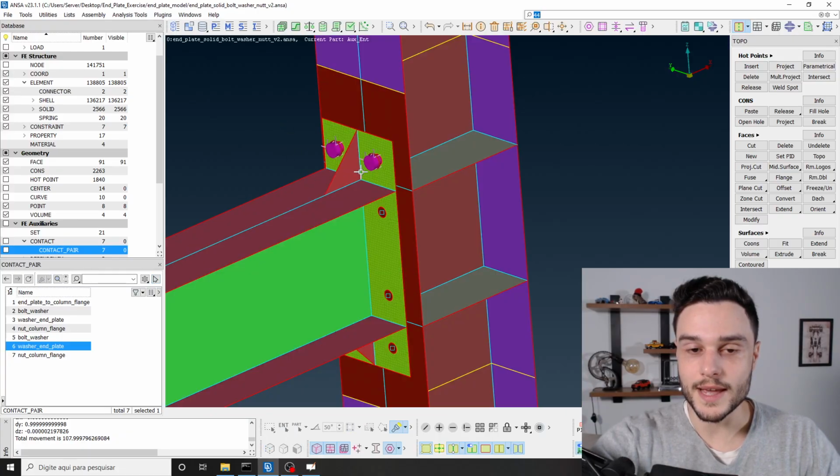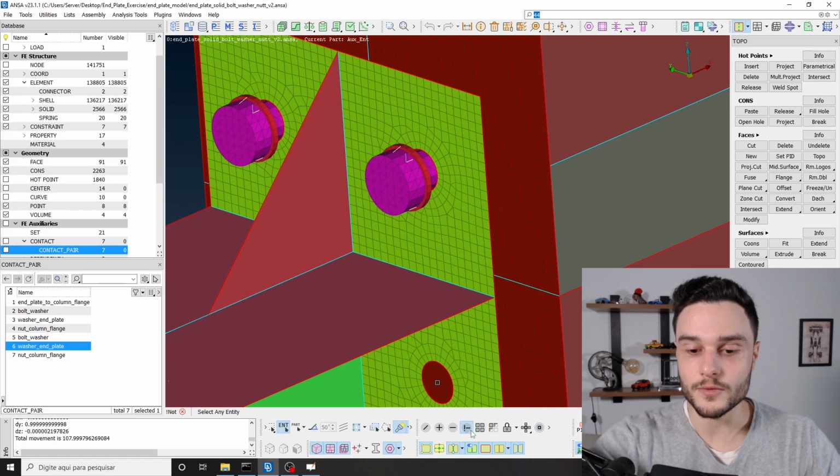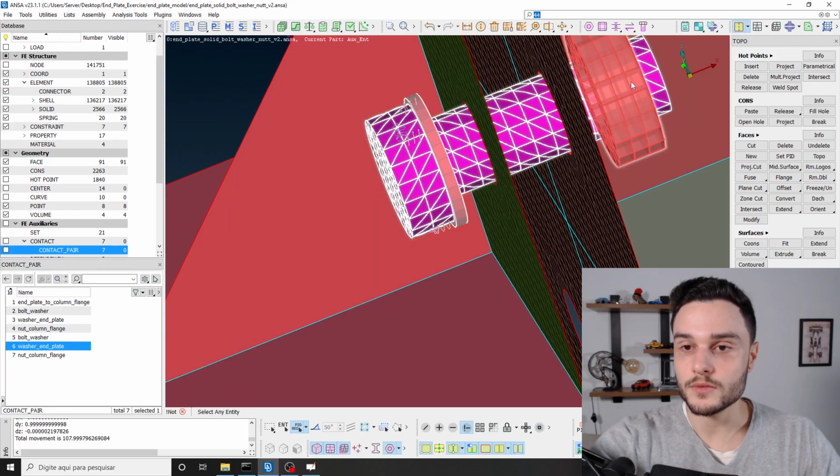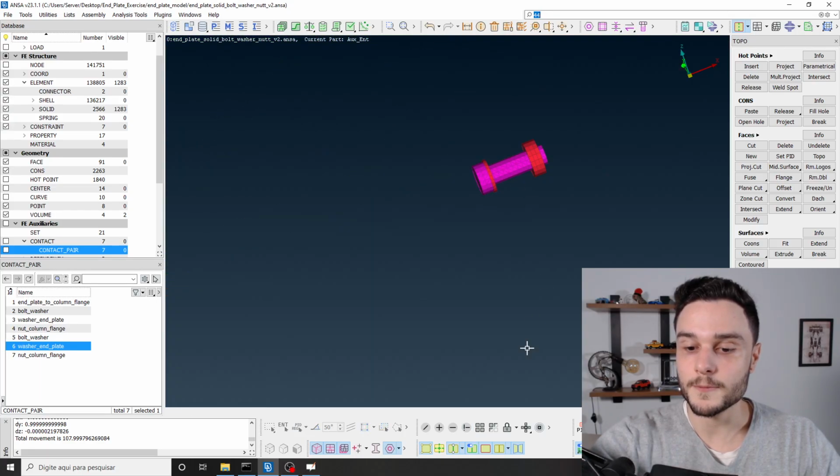So let's do this. Again, we will need to use the not function, property ID selection mode. Or actually, in this case, we will need to use the property region selection mode so that it only selects one bolt. This one, and this one. Middle mouse button again. Neighbor, all.